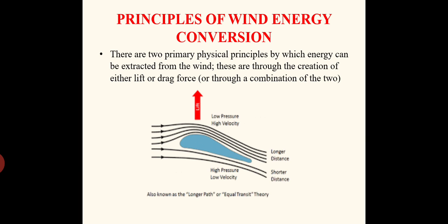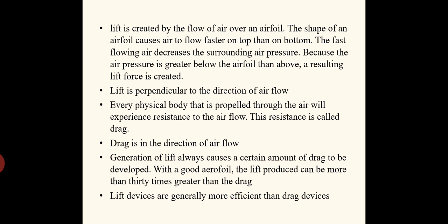Every object is experiencing drag force always, but lift force is created only by producing the airfoil shape or the necessary pressure difference at the lower part as well as the upper part. By creating that pressure difference only, we can create the lift force. But the lift force is much more dominant than the drag force. Always, along with the lift force there will be a drag force also. Lift is created by the flow of air over an aerofoil. The shape of an aerofoil causes air to flow faster on the top than on the bottom.